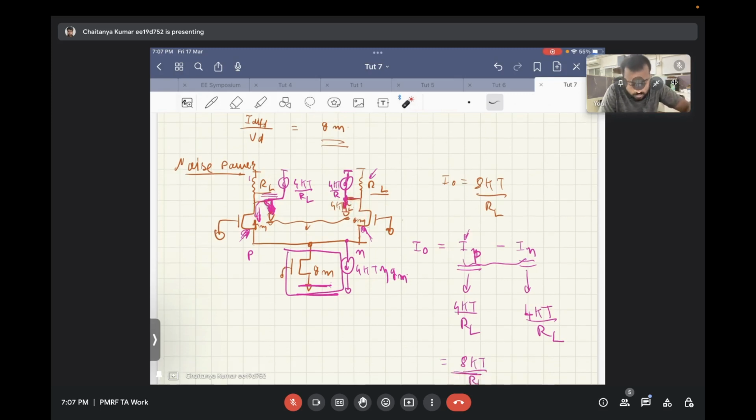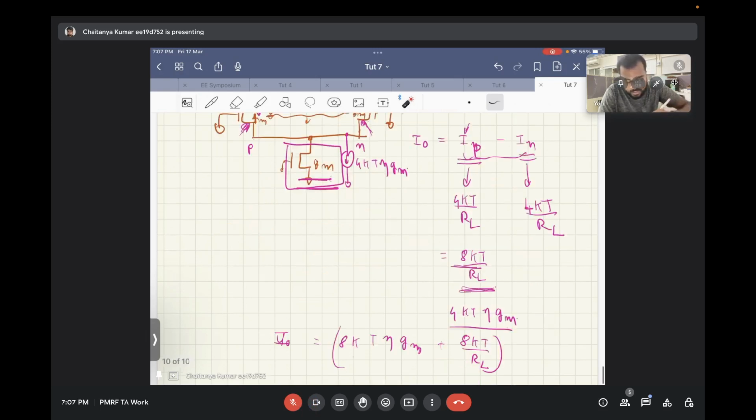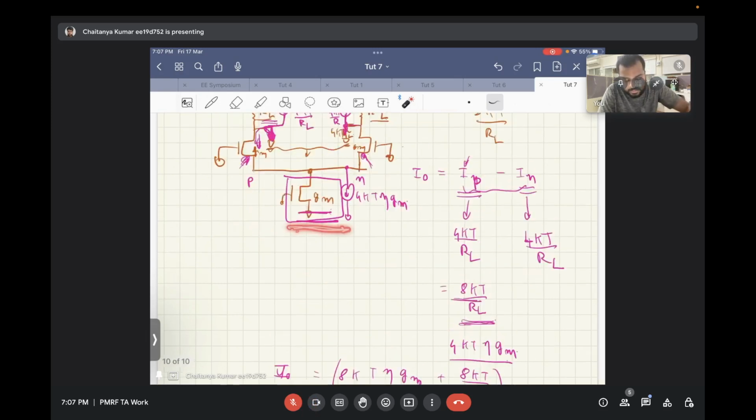So there you should not add power, you should add voltages. And in this case, since this is IP minus IN, you will subtract voltages. Since the circuit is symmetrical, the current will be divided in half, so the short circuit current in both of them will be equal and opposite. So the current contribution due to this tail transistor will be zero. Is it clear?